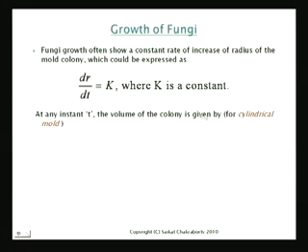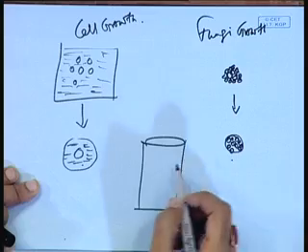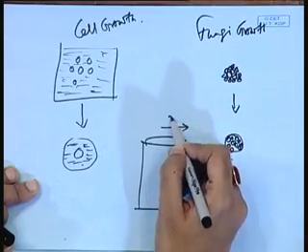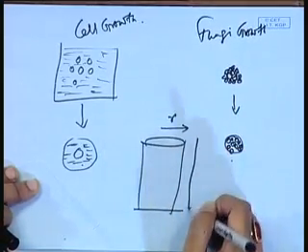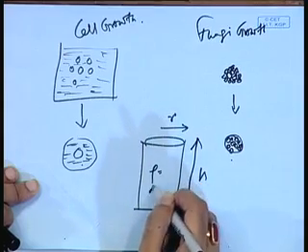And so in the problem that we do today, we consider a cylindrical mold. If you have a cylindrical mold, then x is pi r squared h times rho. Here r is the radius at each point of time, which is increasing, h is the height of the mold, and rho is the density.